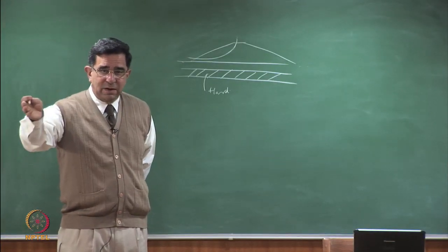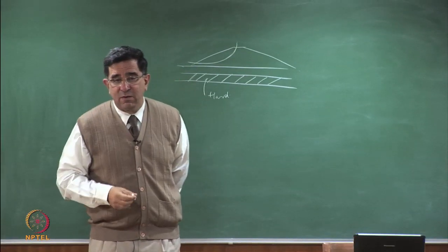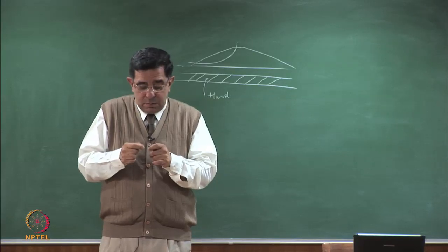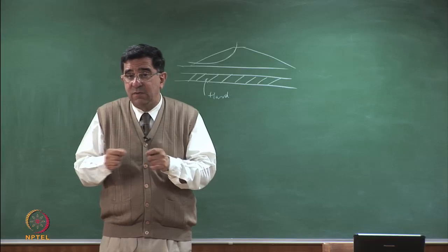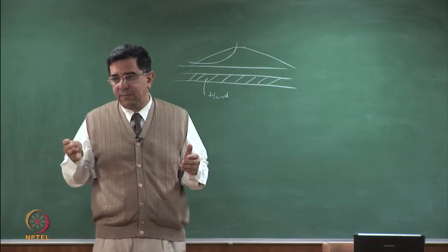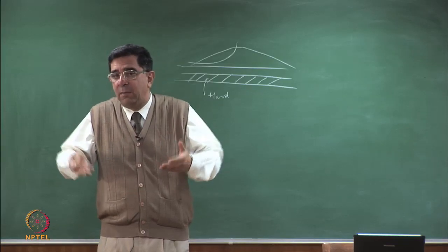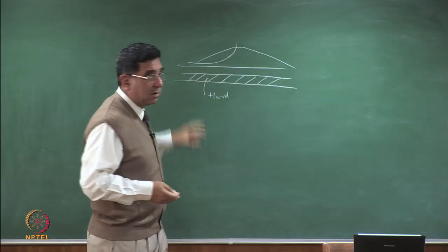So somebody said hard surface, now somebody said weak surface. What kind of weak surface do you have? A failure surface will have to go through a straight line if there is a weak surface along a straight line. If there is a hard surface, the failure surface will tend to remain above it. Like if you have rock, then the failure surface will remain above it.